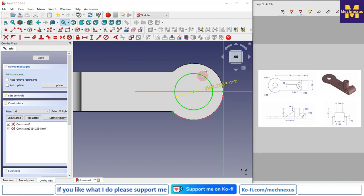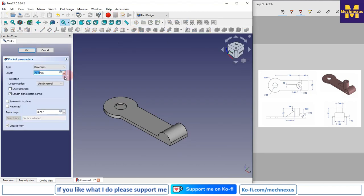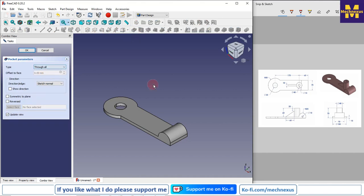Now I will give it a diameter 35. Now I will close it and I will go with the cut, and simply I will say through all.